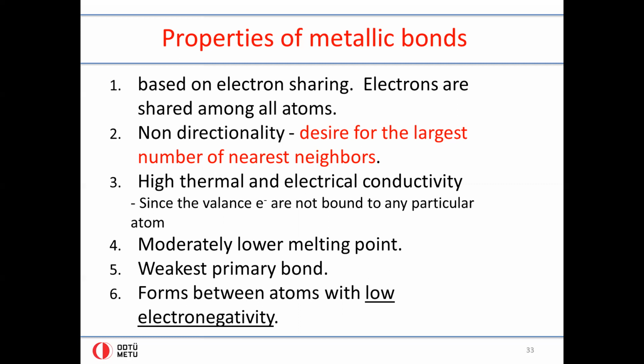So then if you ask the question differently, if I were looking for the highest melting point material for a special application, what type of material would I look for? And the answer would be a ceramic, not a metal, and not a polymer. So a ceramic would be partly covalent and partly ionic, but a metal would be metallically bonded, hence it would be weaker in that sense.